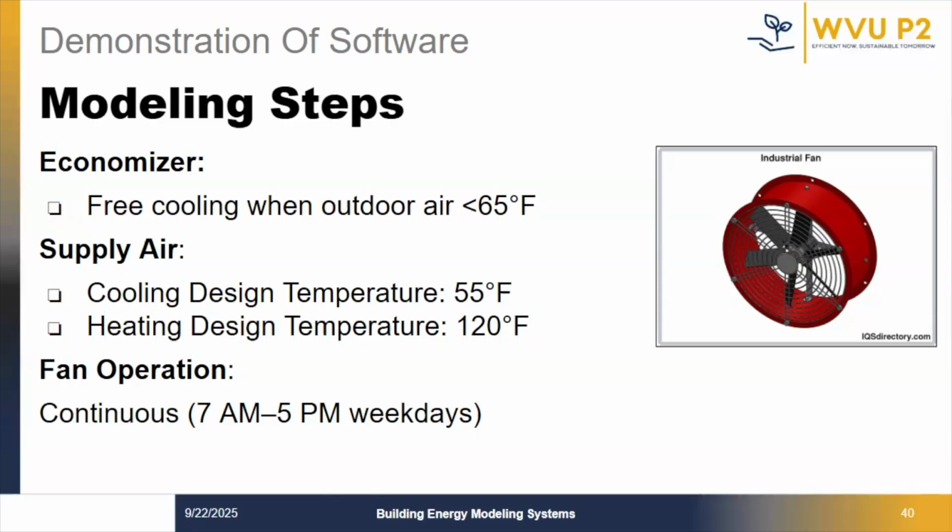Also, the system delivers 55 degrees Fahrenheit supply air for cooling and 120 degrees Fahrenheit for heating, which are the standard set points that balance comfort and efficiency.